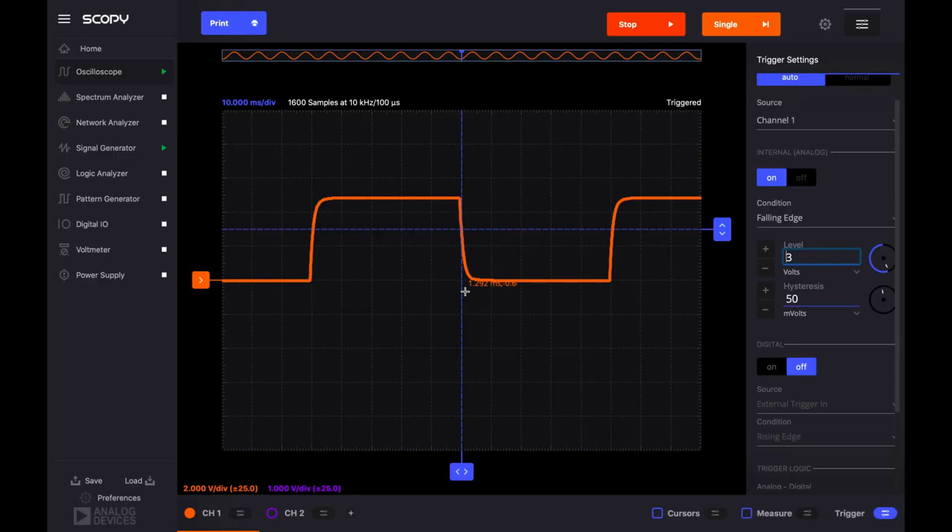It's really cool. You're watching a signal that is traveling some fraction of the speed of light. But what this is allowing you to do, by setting up the trigger method, is line up the center of my screen. And if I scroll down here and try to line this up with t equals 0, right about there, it's about 3 volts. I can't move my cursor that well.